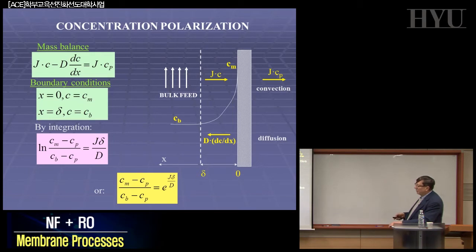Just to consider that no membrane system, what we normally call a membrane separation system, is working in dead flow. That is the case I was mentioning before. All the operations we have been discussing are operations in which the bulk solution is running at high velocity on the membrane surface. You spend energy, but just to facilitate this back diffusion.